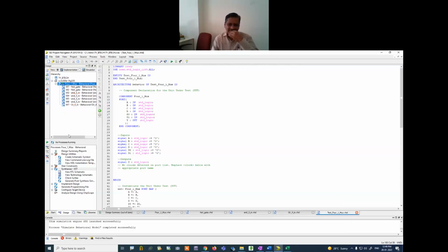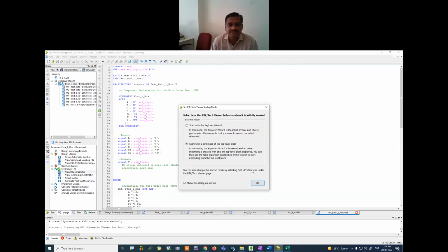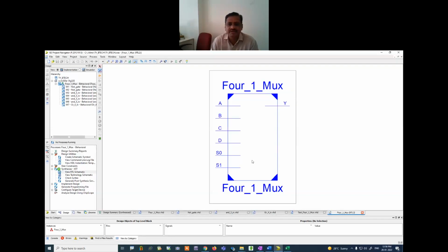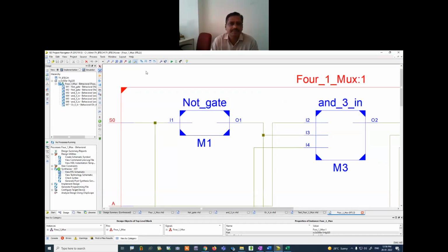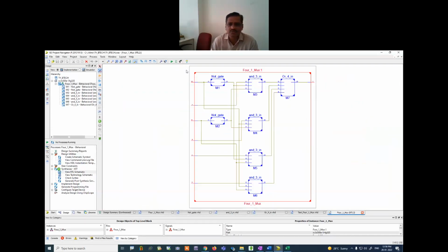Now, we have to take a printout of this whenever we complete a practical. We have to take the RTL schematic. Generally, if I click on the RTL schematic here, it will be synthesized and we are able to see the RTL waveform. But sometimes this window may not be proper, so take it in a single line.